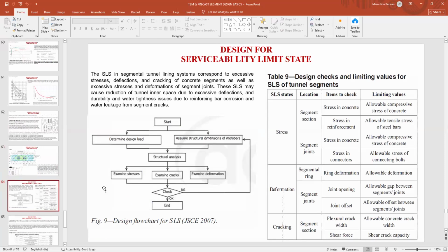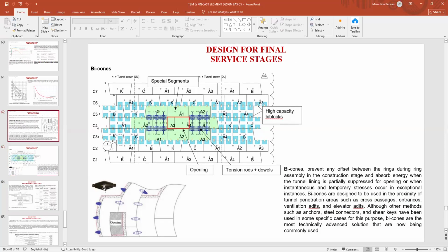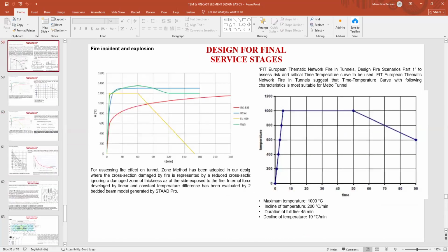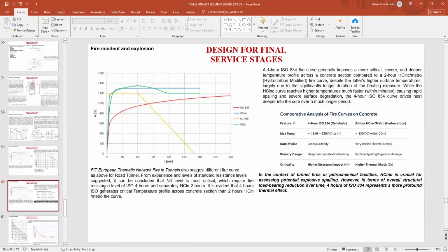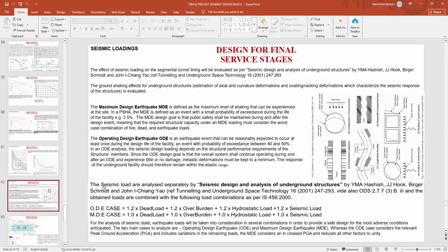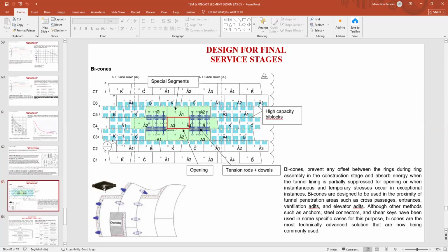Okay. So this is all I discussed. This is called the ultimate limit state condition. Ultimate limit state condition means all your forces at maximum limit you are designing. So all your bending moments, all your axial forces, all your shear forces are taken into consideration in your ultimate limit state. And in the ultimate limit state, you are putting a factor of safety of 1.5 if it is a static load condition. If it is a dynamic load condition, we are putting a factor of safety of 1.2. Okay, is it clear, everyone?